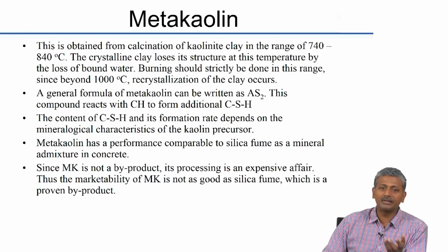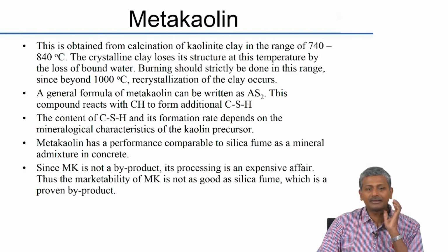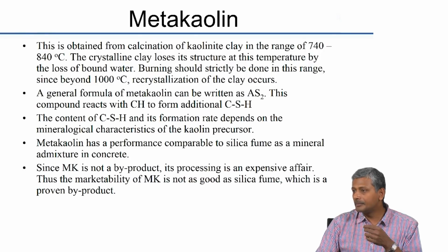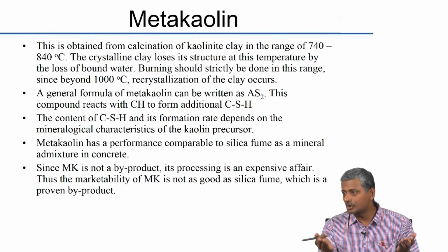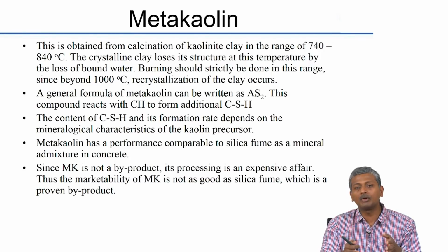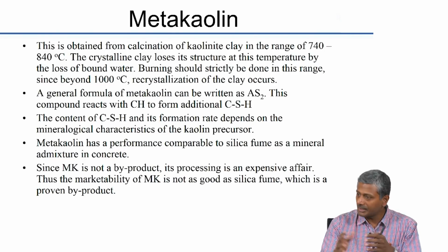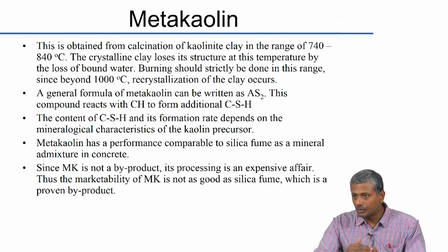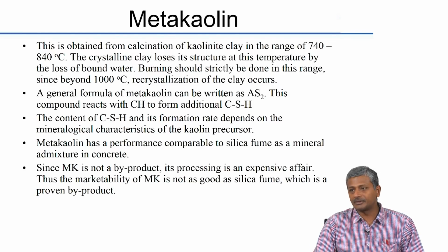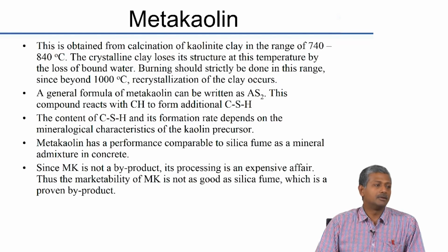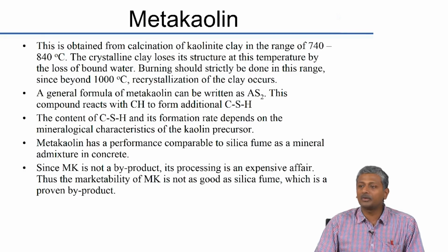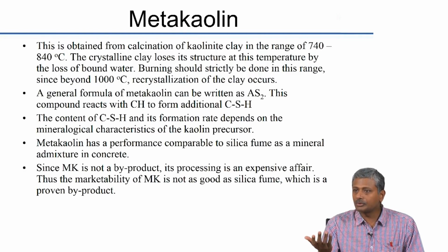Where, in what other industries would they be using calcined clay, calcined kaolin? Sorry, the brick industry, of course, uses the topsoil, but here we are talking about kaolin. The brick industry uses topsoil, mostly it is illitic clay, it is not really kaolinitic clay. Kaolinite is found in layers much below the earth's surface. So, you need to actually mine it to get it. Okay, so, this kaolinite can be mined and obtained and then burnt to form fired kaolin or calcined kaolin.